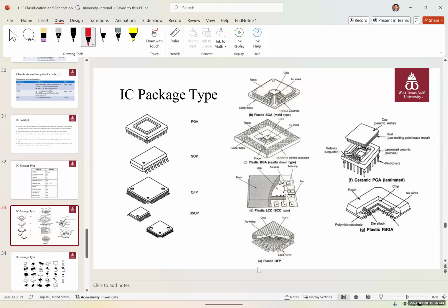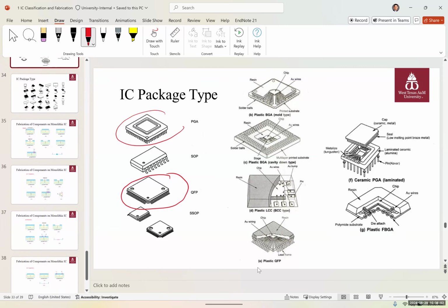We have 2 main methods for all electronic parts to assemble them on PCB. We have surface mounted, which is this one over here. And we have the go-through pins. The go-through pins go through the PCB to the other side, and we solder them. The surface mounted ones, you have to actually solder them on the surface of the system.